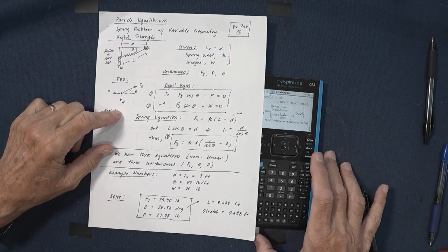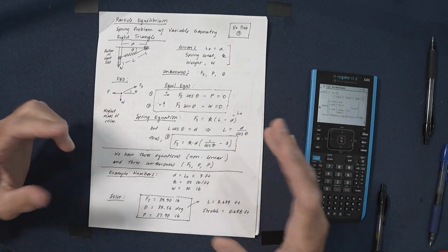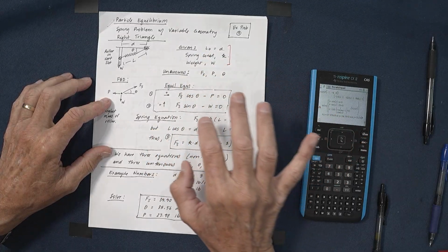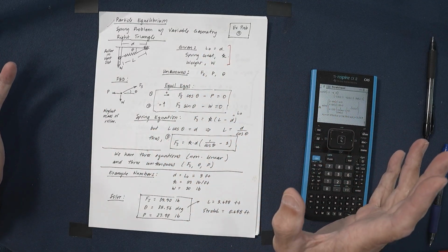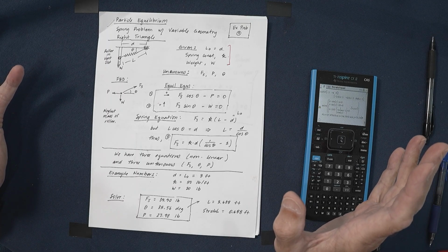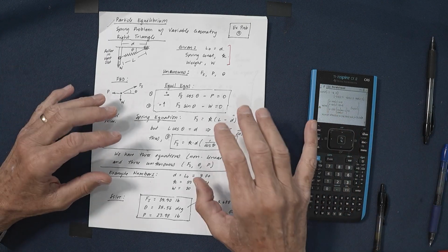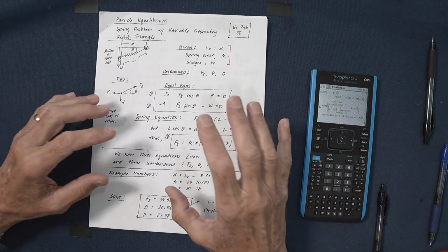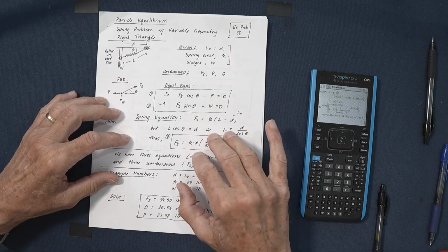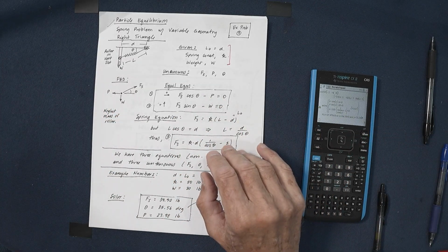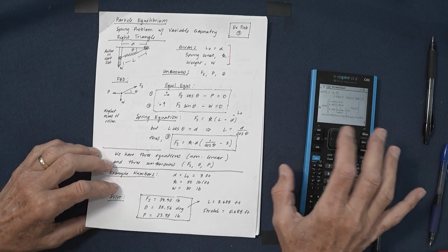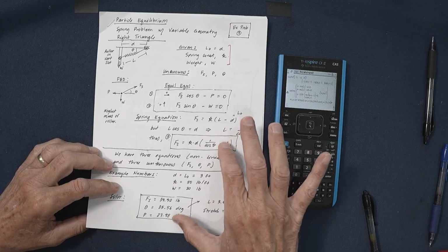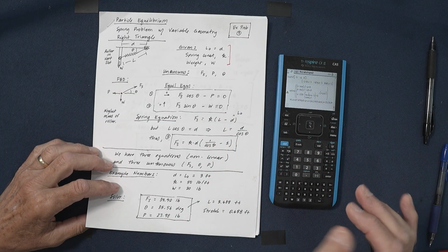Not easy. But basically, you're writing equations that define the system. Free-body diagram, equations, spring equation. 3 equations, 3 unknowns. And so it's classical engineering, systems analysis, writing equations that define the system. If they're linear equations, you can do a simple matrix analysis. If they're a nonlinear set of equations like these, then you have to use an iterative method, which is basically what the nSpire is using too. And again, I'll show you in Excel how to do this in a separate video. So that's this problem.